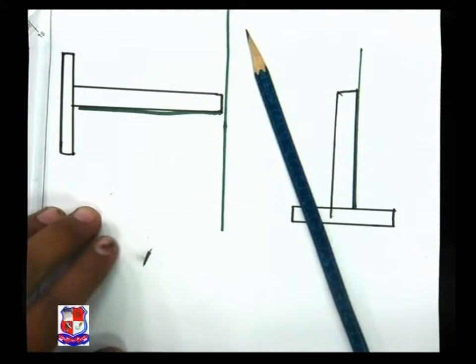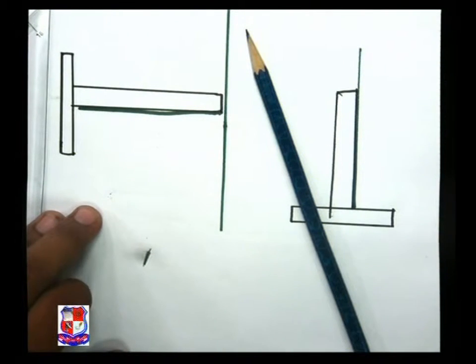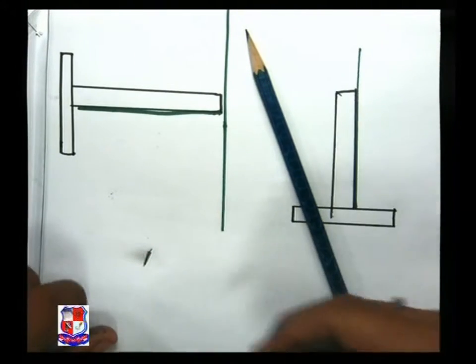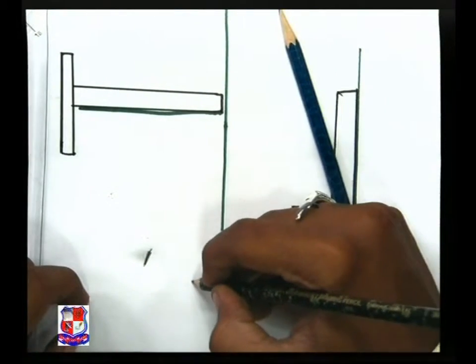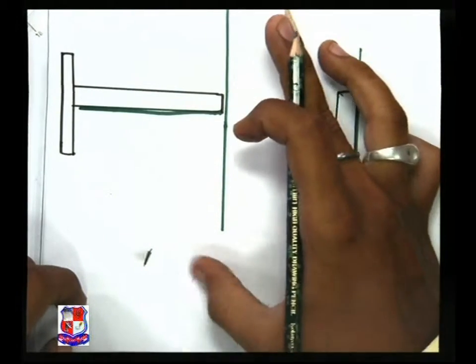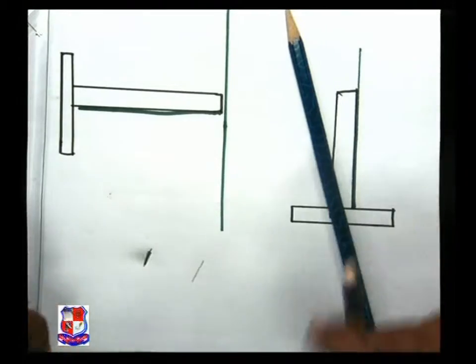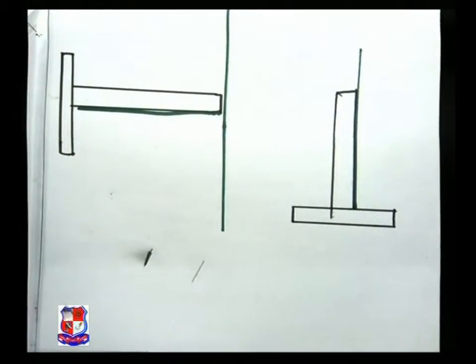If you look at it properly, it smudges, it will blacken your drawing sheet. But if you look at this H pencil, it doesn't smudge. So it is better to choose an H or 2H pencil instead of an HB pencil.